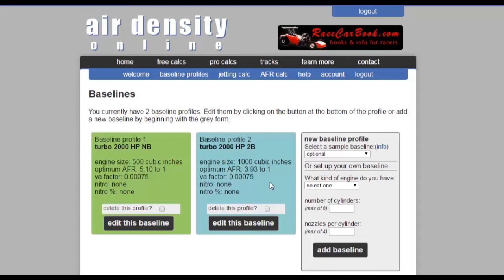It's a real simple setup. 1 set of nozzles, 2 bypasses. You drop 1 bypass off for boost. Using ProCalc, all the nozzles and bypasses are adjusted to get approximately a 5-to-1 air to fuel ratio for methanol at sea level with that jetting, and less than 4-to-1 under boost for 2 atmospheres. And these were developed for sea level weather, and they could all be adjusted and changed for different altitudes if necessary.